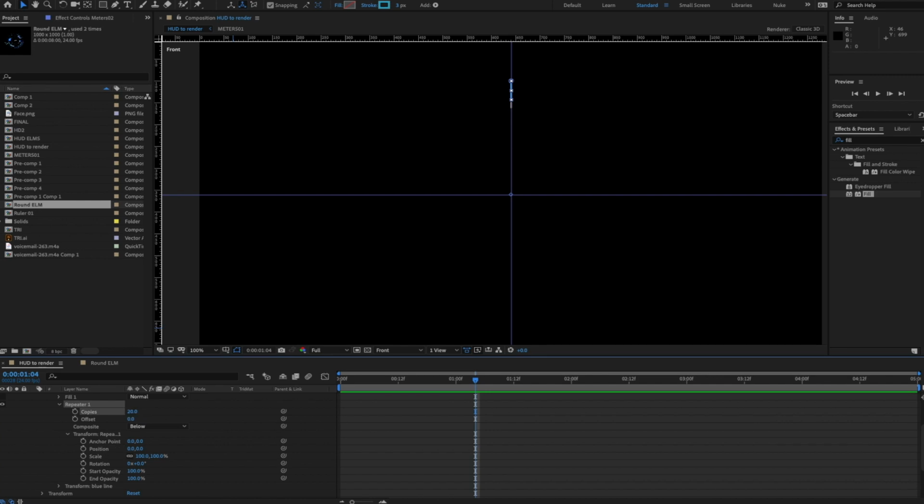Now I want to do a little bit of experimenting here, so I'll make maybe like 20 copies, and if I increase my rotation, I should be able to eyeball what I think looks good in terms of its spread. That's a little bit too far away. There's too many gaps here, at least in my opinion. So I'll decrease the rotation, holding down the Command button as I do that to give me a little bit more control. Maybe something like that would be a good spread. And then I'll increase the copies, also holding down Command, to make them go out until it meets right about there perhaps. So I think that's a good spread here.